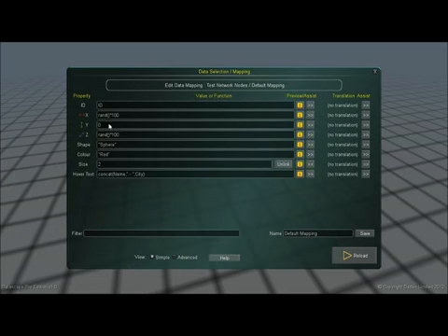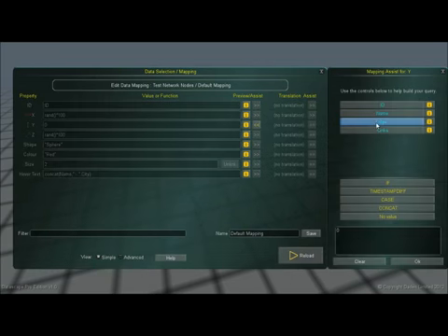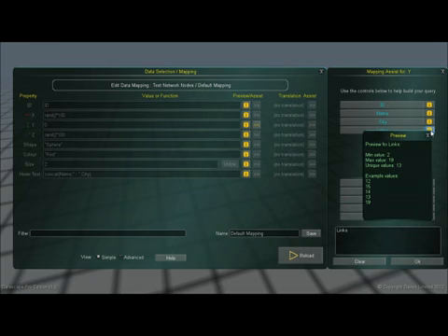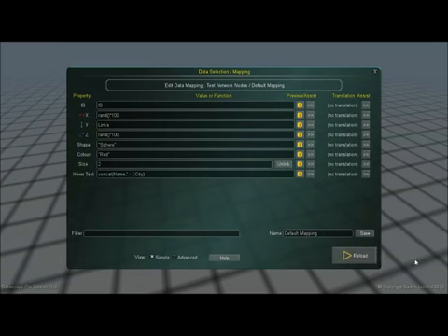The other thing we might do is offset in the vertical dimension, and within the data we've got a count of the number of links. So that could be quite useful. Just get rid of the 0 there. So basically the vertical offset is going to be dependent on the number of links a point has. We can use preview here to see that's going to give us a value between 2 and 19, which seems reasonable for the offset.